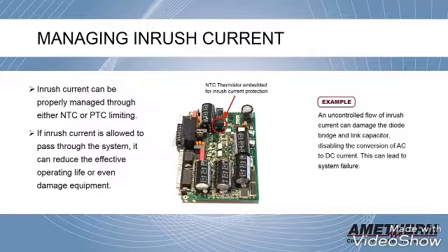As you can see in the photo here, an NTC thermistor has been embedded for inrush current protection. Without this thermistor, an uncontrolled flow of inrush current can damage the diode bridge and link capacitor, disabling the conversion of AC to DC current. This can lead to system failure.